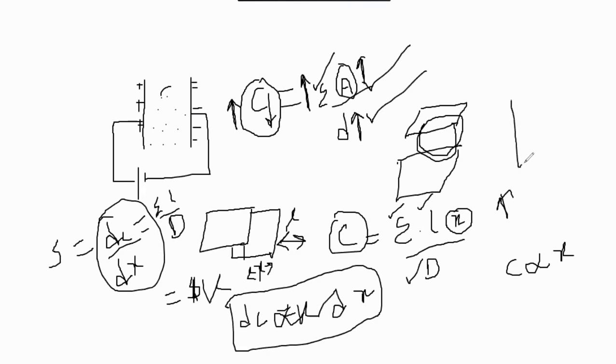So obviously it will provide a linear relationship if we plot the curve. This is your capacitance and this is your displacement or overlapping area. It will show a linear curve because k is a constant and dC is proportional to dx. This is one characteristic of the capacitor transducer, between the capacitance and the displacement. So this is the first condition, changing the overlapping area. This is a very simple explanation.